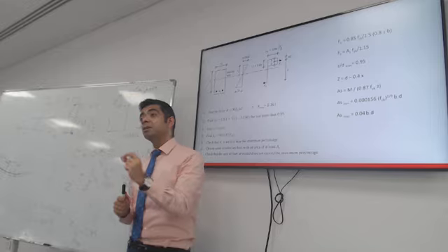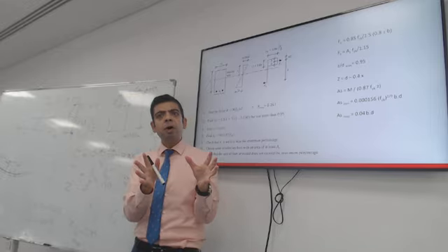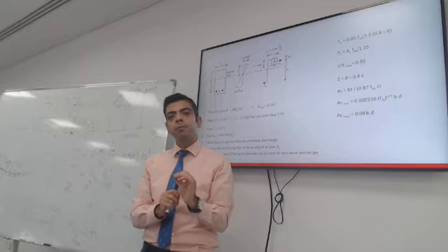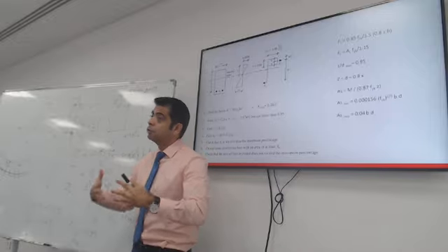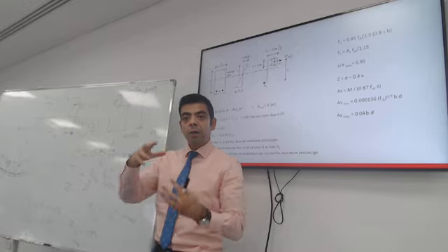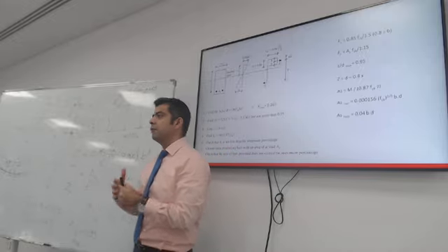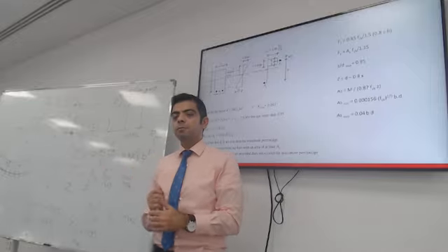Because this material is called reinforced concrete. If there is no reinforcement, it's plain concrete and it behaves completely differently. So you always need to have minimum reinforcement. This minimum reinforcement is to control cracking, to control shrinkage, and to control other types of behavior of concrete. If you don't put reinforcement, the cracks will be very wide. So you need minimum reinforcement for that.